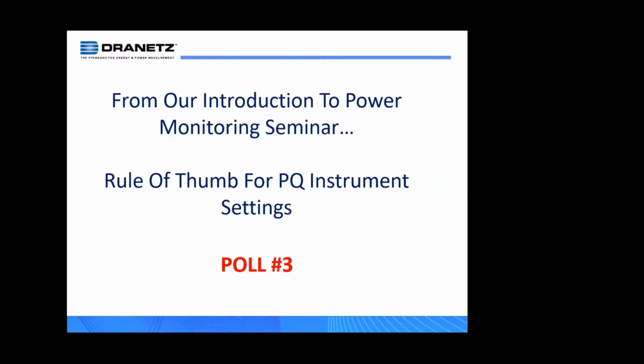And in fact, a lot of the instrumentation, including Dranetz instrumentation, the default settings for power quality measurement is 10%. Of course, with the Dranetz instrumentation, you have the ability to go in and adjust it depending on the application. But in such instrumentation that do not allow you to go in and readjust the thresholds, it's usually defaulted at the 10% tolerance there. But ideally, if you can match the nameplate information on the equipment, that would be ideal to do. If you can't, you can use the 10% rule.